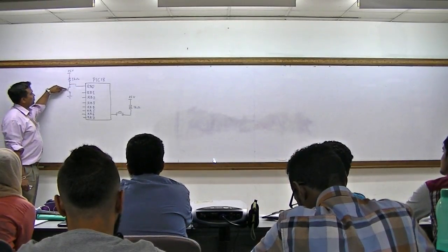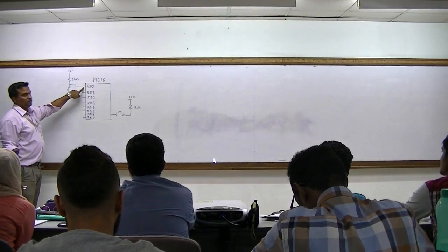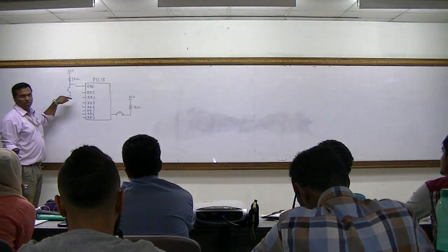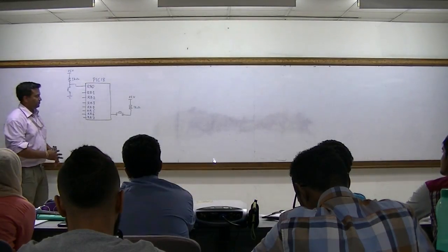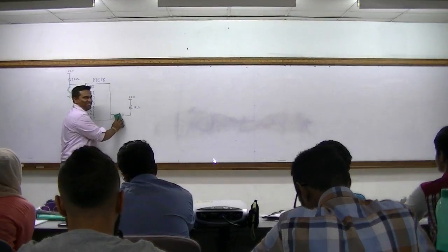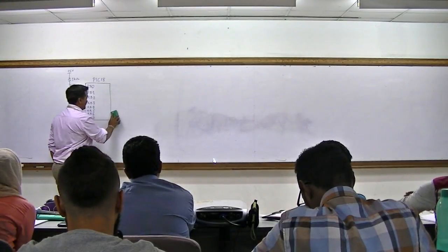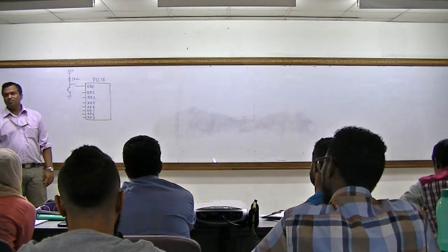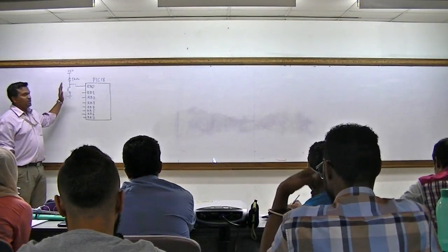So when the switch is not pressed, what is the logic at this pin? 1. When the switch is pressed, what is the logic at this pin? 0, because we are shorted to ground. You understand? Yes or no? Okay. So this is the input part.